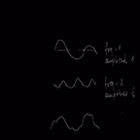So let's switch to Houdini and see this in action. If inside of Houdini you click the turb noise operator and go to the parameters, you find these parameters here. And you have the roughness and the turbulence. And the turbulence is the number of octaves. At the moment it is set to 5.